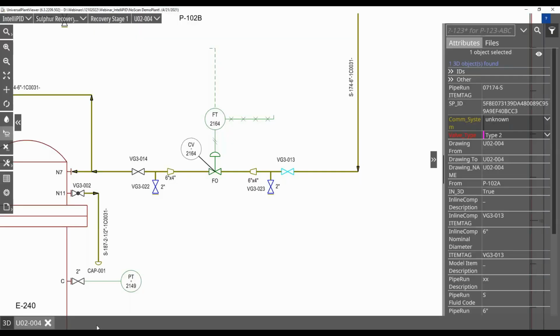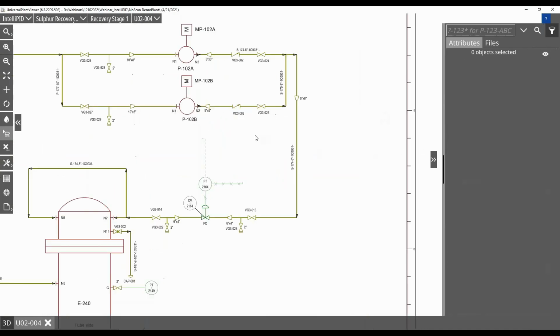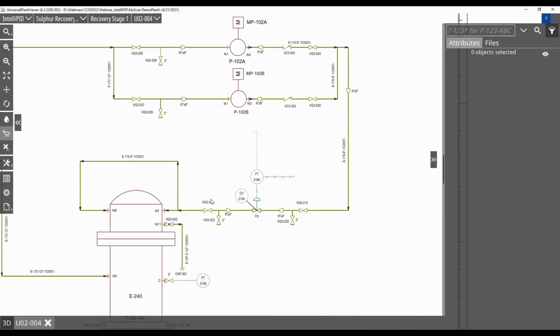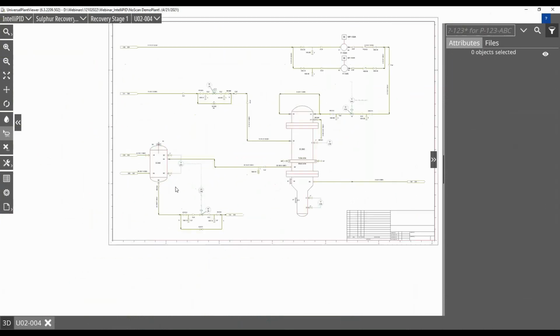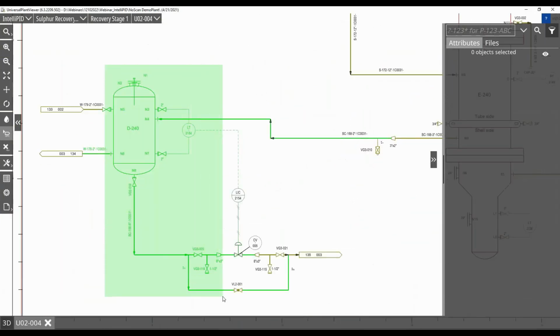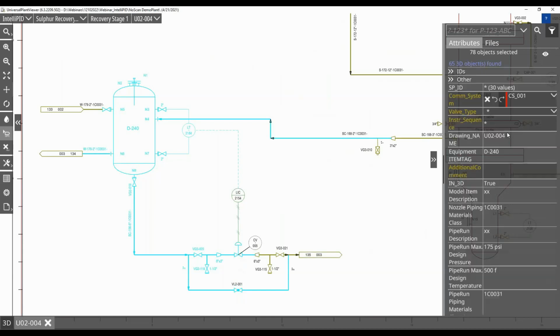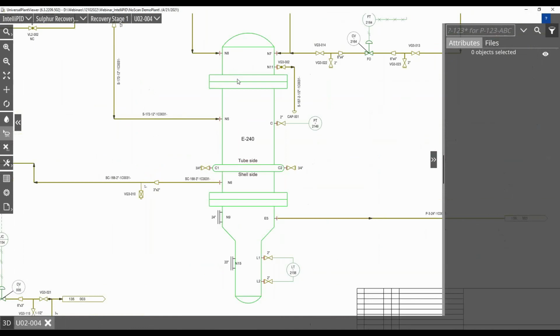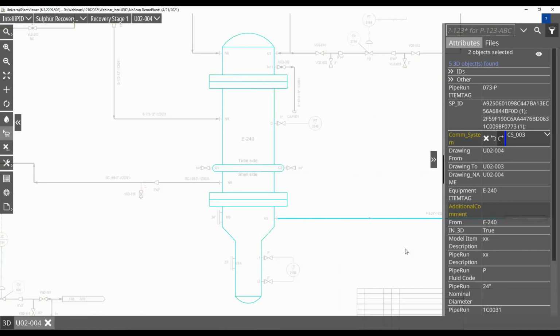I will now switch to the next topic. I will deactivate the valve assignment so that everything kind of changes back to normal. And now we are going to start with commissioning system assignment. We will start down here, select the complete area, and assign these values to commissioning system 1. Then we will take the heat exchanger plus the pipe going out and assign it to commissioning system 3.